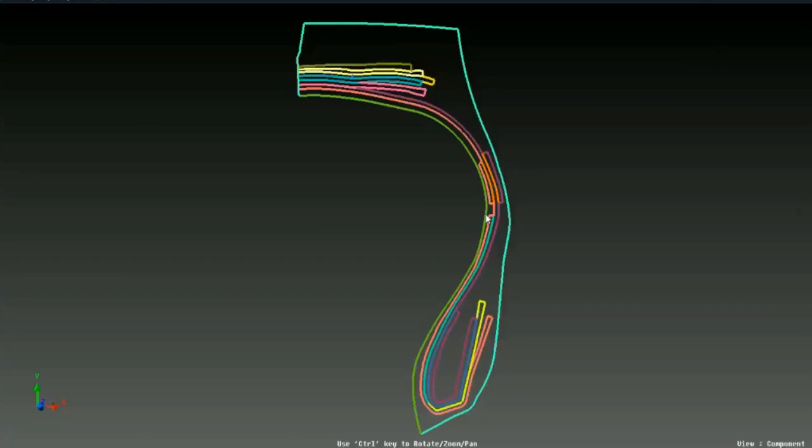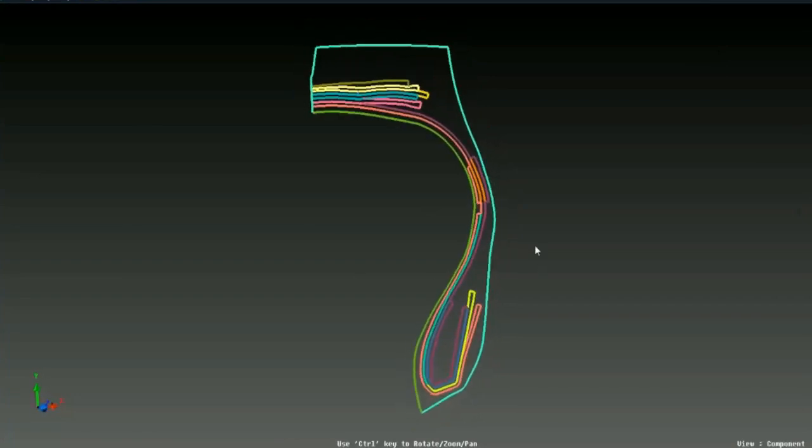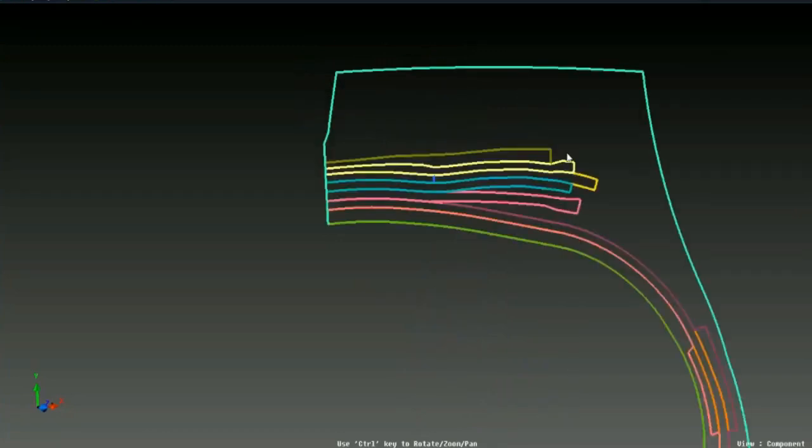So our first demo would be on 2D modeling of a tire for stiffness analysis. Here we see CAD input data which we get from the CAD engineer for 2D modeling of a tire. This cross section would be an end-to-end section where the inner portion of the tire would be for the pressure load area and the outer portion would be for the carcass. And also we see here some CAD curves inside. These are nothing but the reinforcements of the tire.